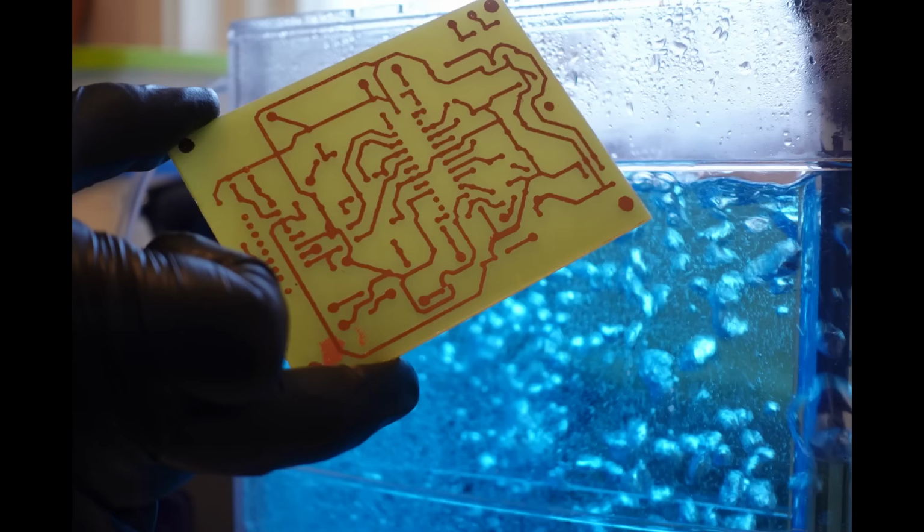Etching doesn't happen evenly in this tank, so we have to move it around a bit. If you leave the board in for too long, some of the protected copper can start to degrade. If you don't have a tank like this, a small tub on a countertop works too. About 20 minutes later, it was starting to look done, so we took it out and rinsed it off. Finally, the remaining photoresist can be rubbed off with some acetone.